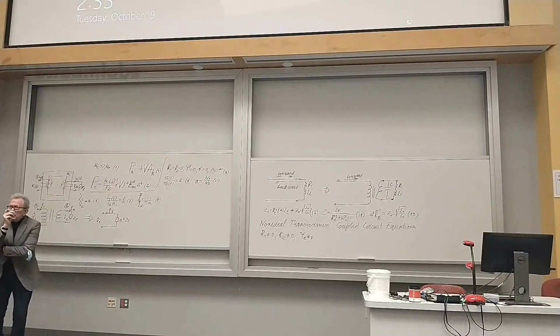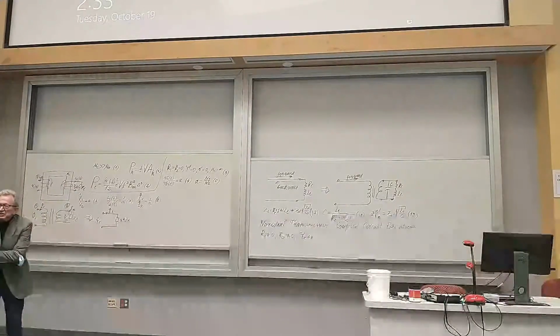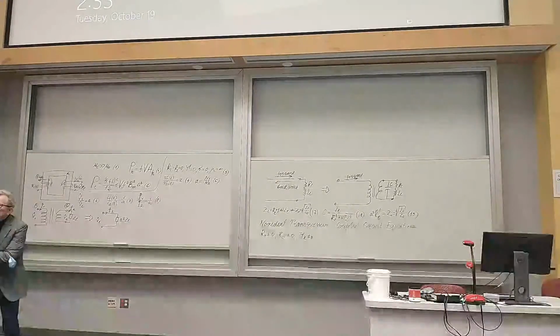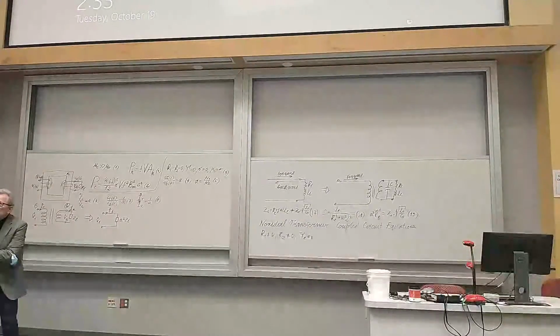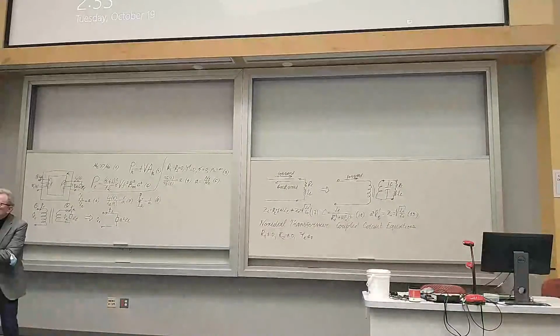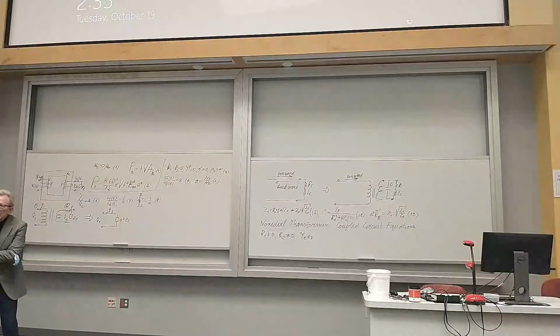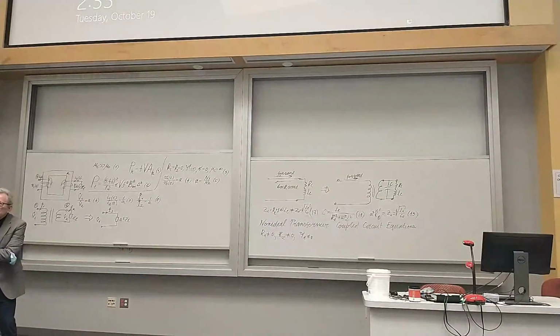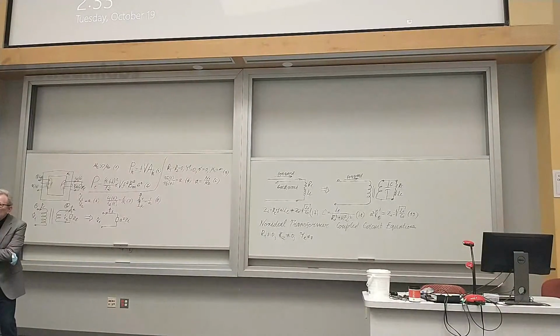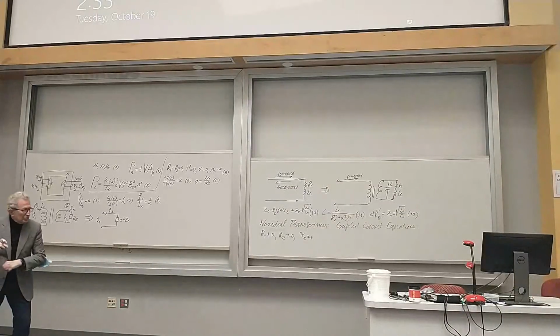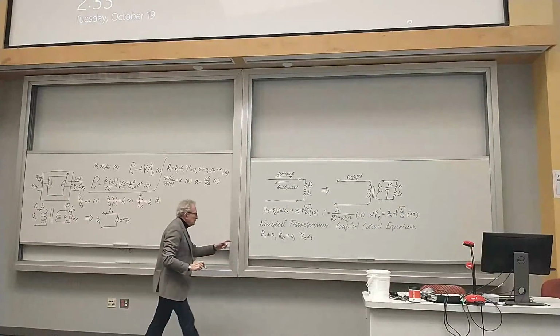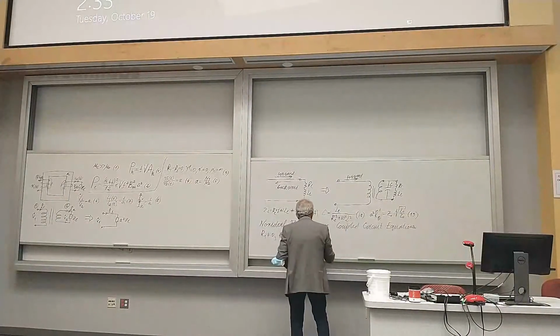And this very small number, it turns out, determines the properties of a power transformer. They will result in so-called leakage inductances. I would like to challenge you to find any other area except power engineering where they deal with leakage inductances. That is why this is a very important assumption.